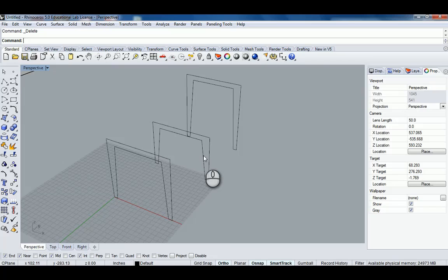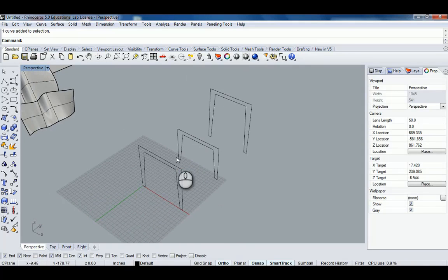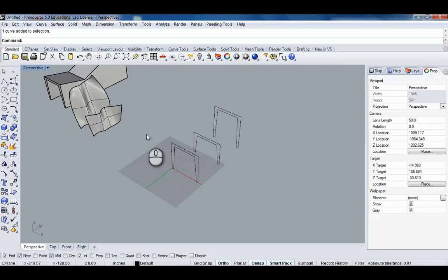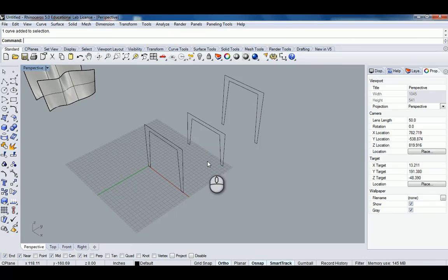So another surface creation command that I think is very powerful. Again, you can use cross-sectional curves. We can use the curves that we had made before, but just to illustrate this example here, is sweep. So sweep adds another layer of dynamism to a surface that you're creating. So loft is taking the simplest set of data between each frame or each line that you've created, and it's finding the simplest path to extruding that data. A sweep will actually use basically two or even three sets of data to create a potentially more dynamic shape.